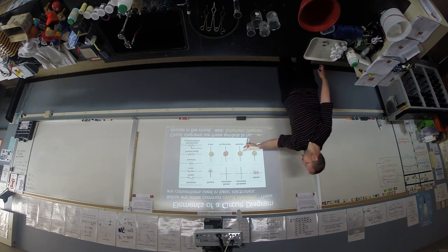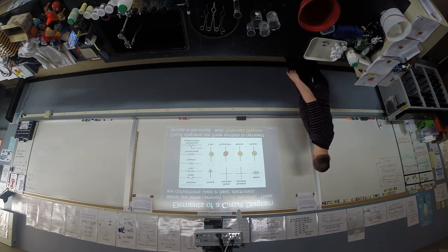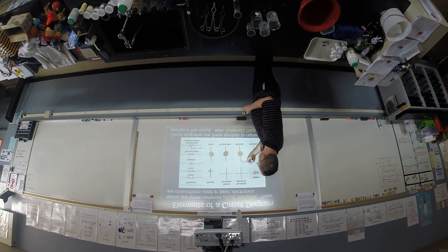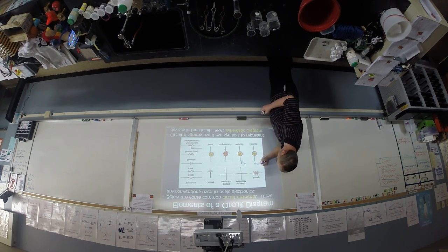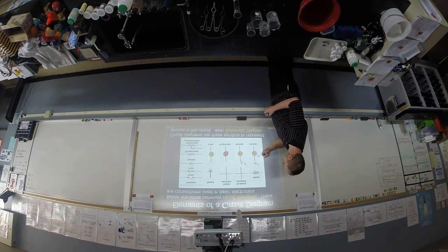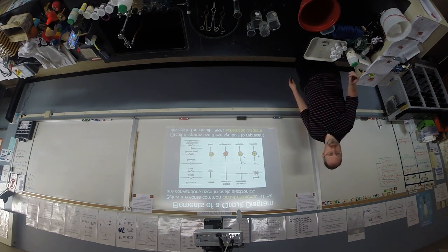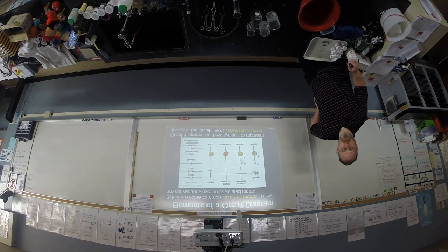Anyway, here's your battery. Voltmeters are usually a V with a circle around it. And voltmeters must be in parallel. This will make sense in a second. Ammeters must be in series. These measure amps, and these measure volts. Voltmeters must be wired in parallel, before and after a device, which we did earlier. And ammeters must be wired in series, right before or right after a device.